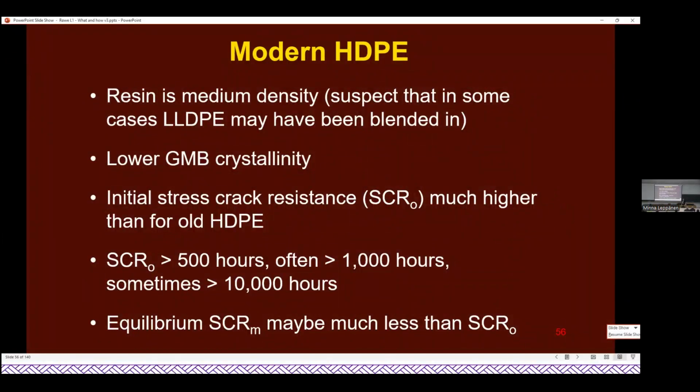I don't have time to go into it in any great detail today, but the number the manufacturer tells you is a fiction. It's not the real material property. It is the property that comes from a test conducted immediately after manufacture. It is a product of the materials and the residual stresses built up in manufacture.